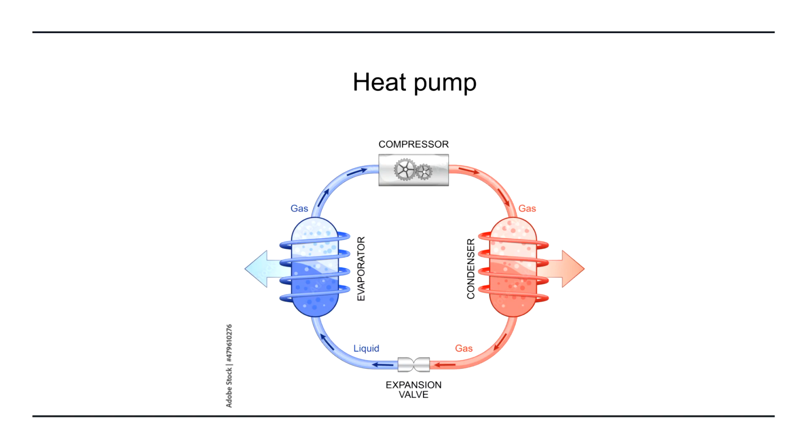Now, the real big thing that goes on in here, so the expansion valve is probably the brains of a refrigeration system. But in order to protect the compressor so that it only gets vapor when we switch from cooling mode in the summertime to heating mode in the wintertime, we need a reversing valve in there. And that reversing valve is the one piece that actually makes the whole thing work, to be able to switch the evaporator coil with the condenser coil.